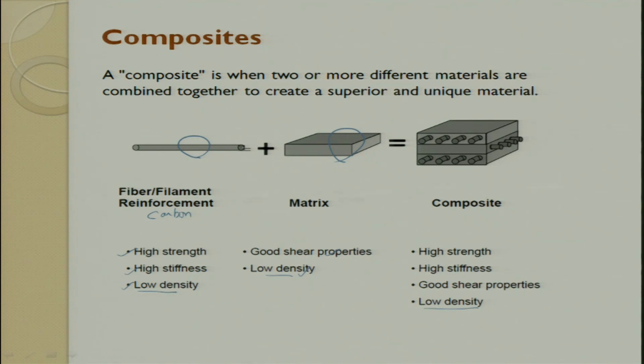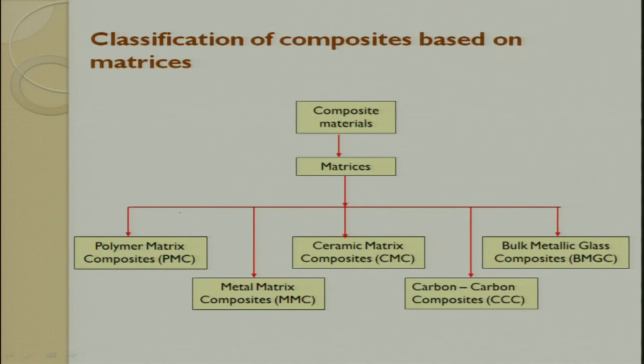So, when I said matrix is made out of carbon, since we have studied about the ceramic matrix composite, what should come to your mind is we will try to use a polymer, we will do pyrolysis and it gets converted into carbon. So, this should be the basic thought. We will see the process whatever we have lined up here.